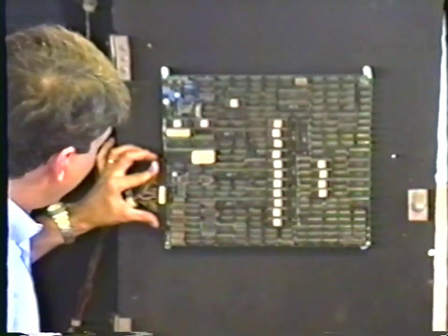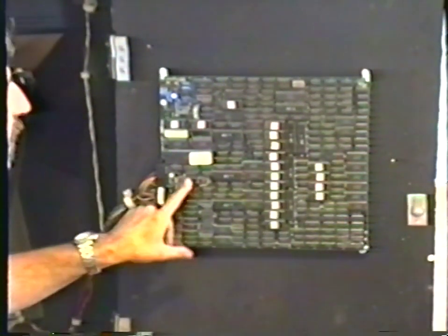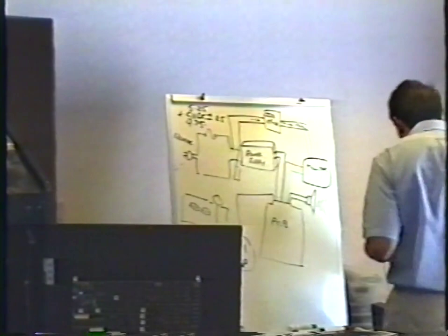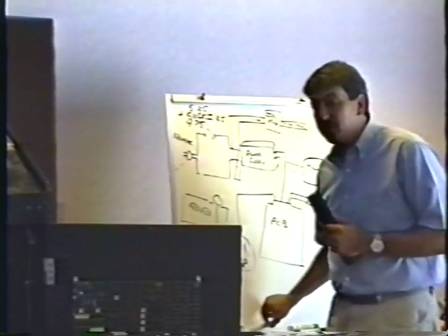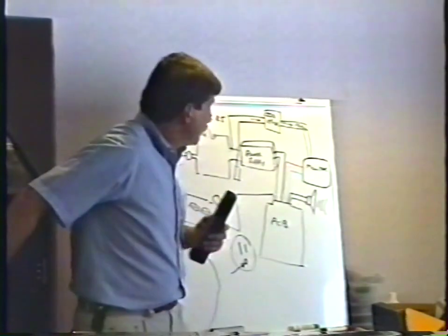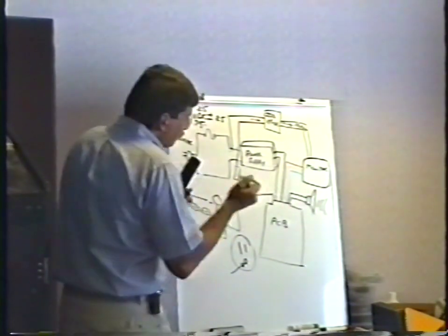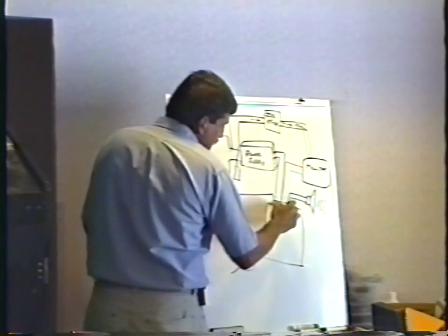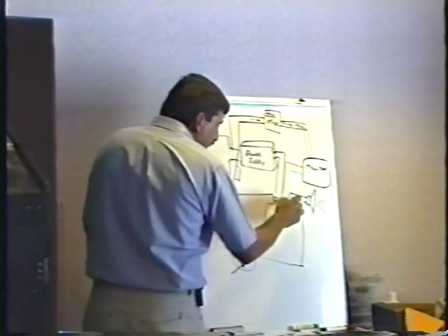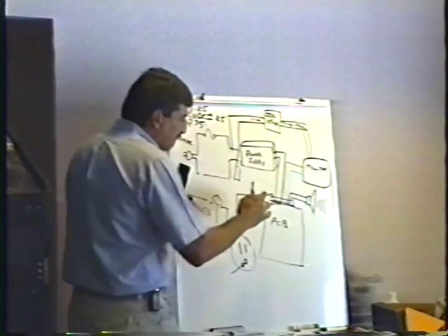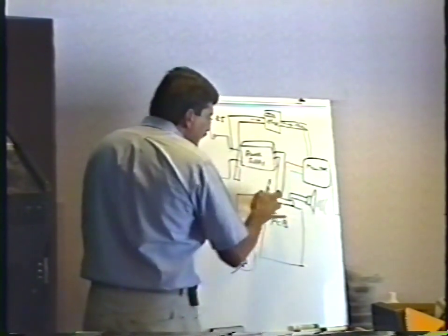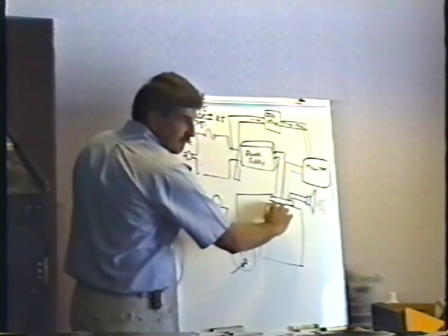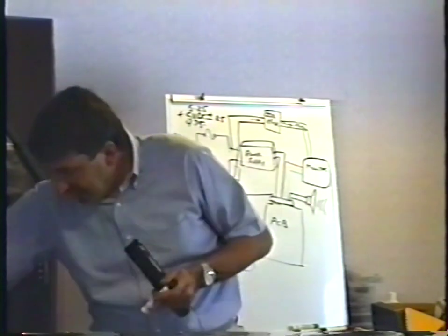Well, the important thing is to check the voltage on the logic board itself. I don't really give a rat's ass what it is at the power supply. I want to make sure that it's exactly 5 volts on the logic board. So where I check the voltage is here at the connector, on the JAMA harness. When the connector that's on the wires is connected to the card edge, there's a little bit of the little plated finger sticking out from behind it. In the game, this thing is called,